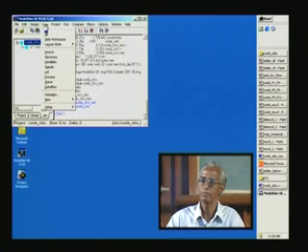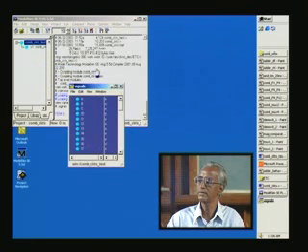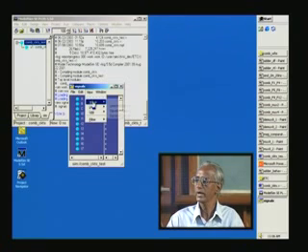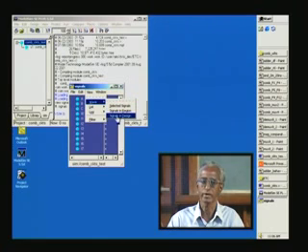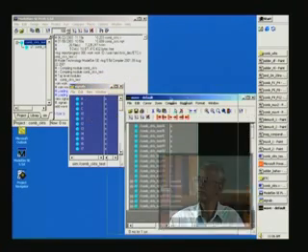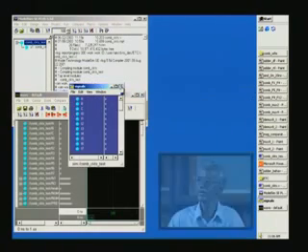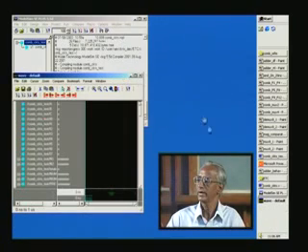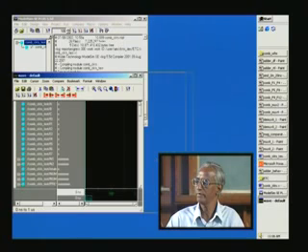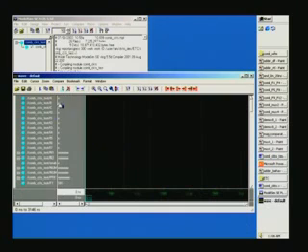So you use view and then signals. Click on signals here, and it opens the signals window. In this you see view, and under view you have wave, and then go to the last option called signals in design. When you click on that, the waveform is opened. You don't require the signals window, so you can dismiss it. Now this is the waveform window, and right now it is blank. If you run this, you notice that you have all this listed.